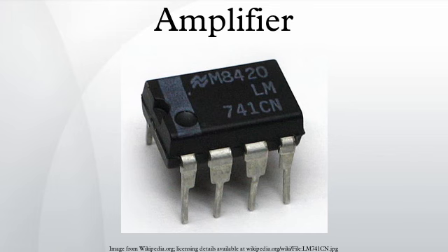In most cases, an amplifier will be linear. That is, the gain is constant for any normal level of input and output signal. If the gain is not linear, for example, clipping of the signal, the output signal will be distorted. There are however cases where variable gain is useful. Exponential gain amplifiers are used in certain signal processing applications.